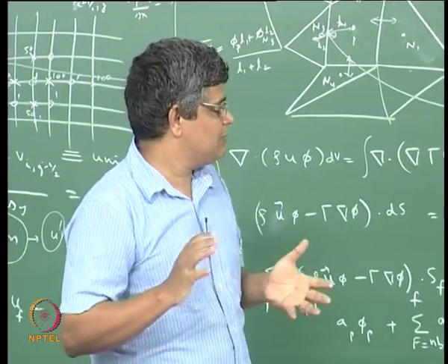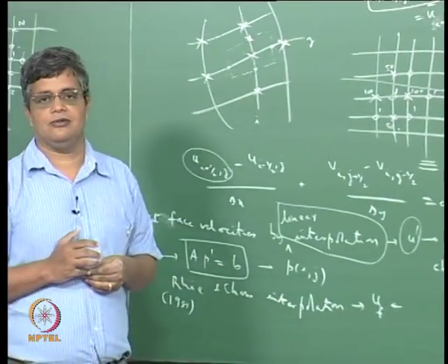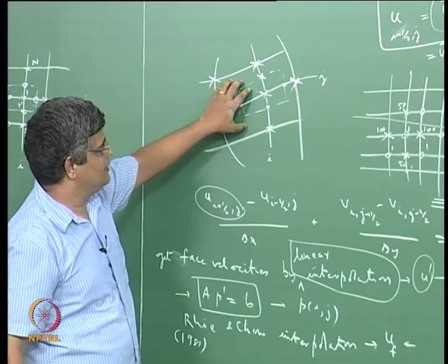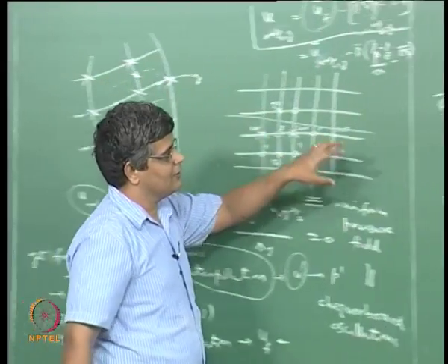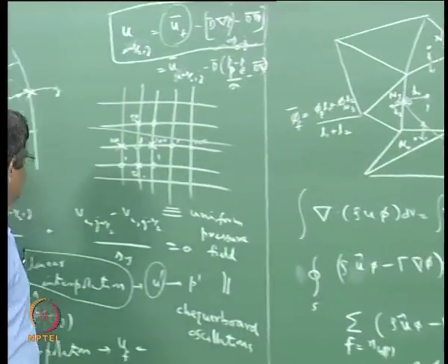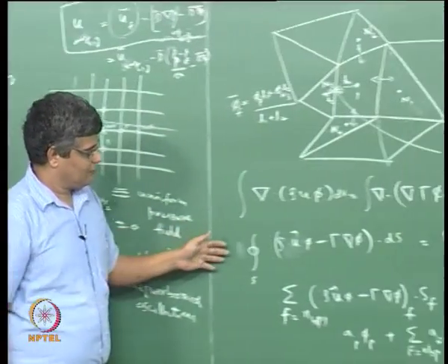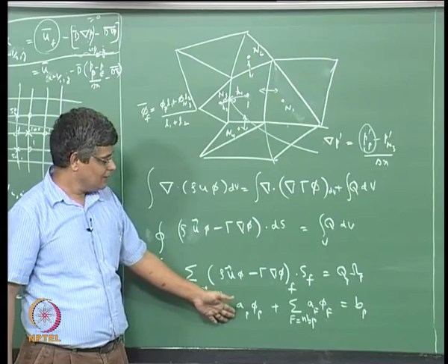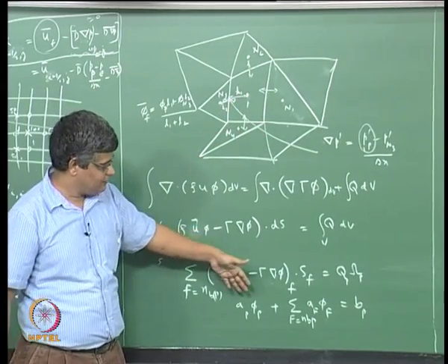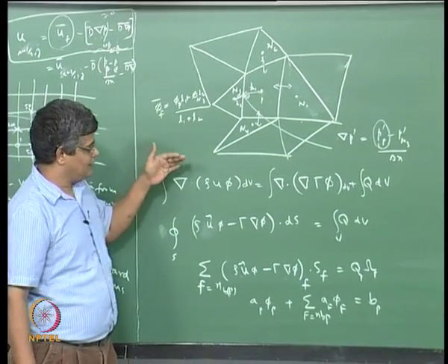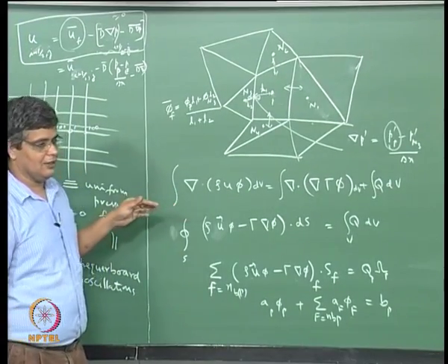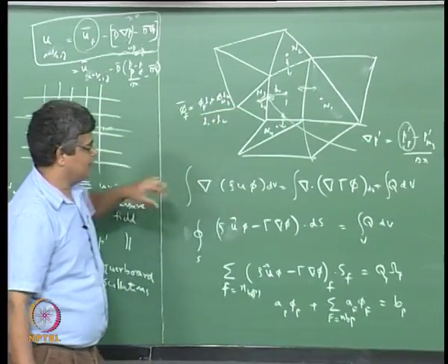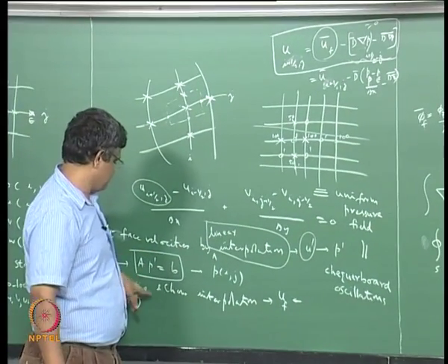And once we do that, we can deal with a single grid, and we can get an overall solution. So in this way, one can see that when we are dealing with complicated flows with respect to geometry, we can represent the geometry either in a structured body fitted grid or in unstructured meshes, and we can adopt more or less the same procedure to convert a given partial differential equation into a discretized algebraic equation like this, and then convert this into a phi equal to b and go through the overall solution process, and we can solve any number of equations including for turbulent kinetic energy and all those things, and in the evaluation of pressure we have to use the collocated approach correction proposed by Rhie and Chow.